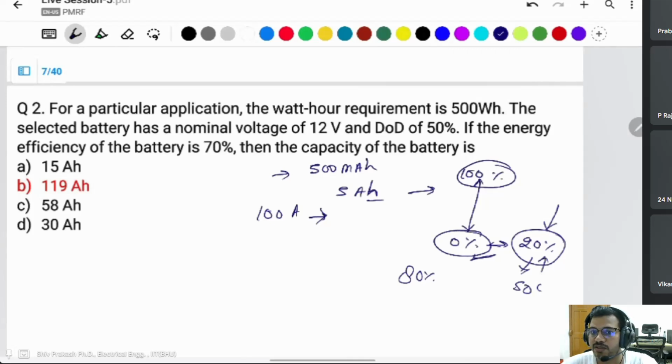It means your battery is discharged 80% and 20% is remaining there. You can't discharge this remaining part. You can discharge only 80% of the battery, it means you can use 80% of its capacity. You can't use 100% of the capacity. That is known as the DOD, so the DOD of that battery is 80%. SOC is a different thing and DOD is a different thing. SOC means how much charge is remaining, and DOD means how much of the battery's full rated capacity you can discharge.